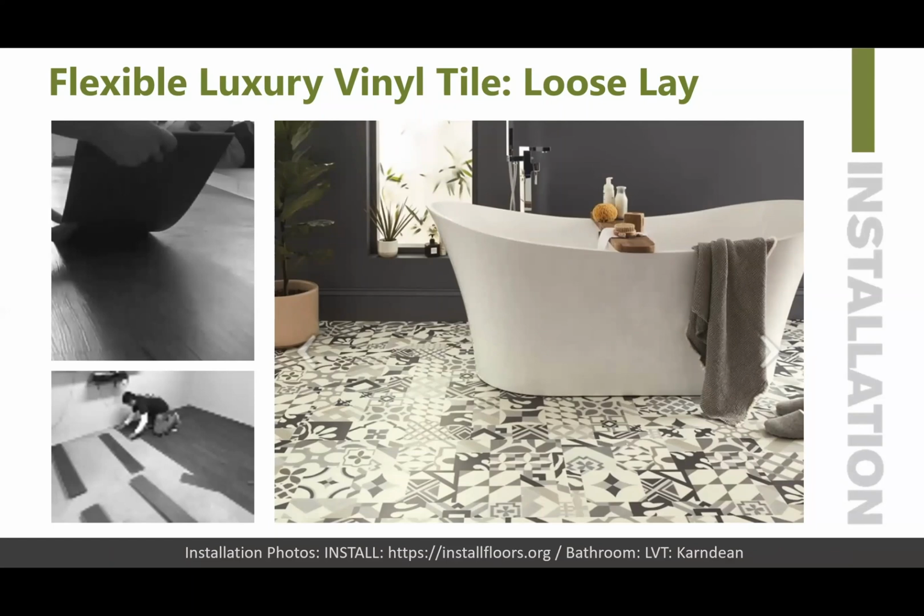So you could reuse the flooring material. Loose lay is ideal for raised access floors. There are some restrictions to this as well, but for the most part, loose lay LVT can easily be installed over most raised access floors, especially those that may require frequent access. Loose lay has a higher sound rating than traditional LVT. Traditional LVT typically will not contribute significantly to sound reduction, whereas loose lay LVT is a thicker product with a textured back that offers improved sound testing results, helpful in corporate, multifamily, or other hospitality installations.